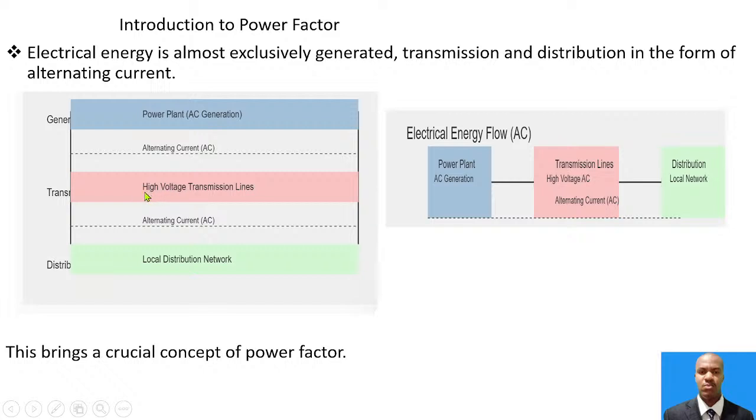After it has passed the transformer, it enters the transmission lines, and these lines operate at a very high voltage with very little current. The reason voltage is high with a very small amount of current is to minimize the line losses, because our transmission channels are mainly made of aluminium, and in most cases copper. So we are trying to minimize the power loss along the transmission lines.